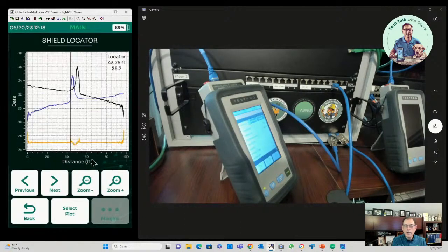Now I'm going to zoom back out. We can see these step TDR traces as well. Now these actually give us a little more detail because they jump up and then come back down, and they're a little more accurate in the details. And these will find very small details. So if you notice, the spike doesn't look very big here at this midpoint on the pulse TDR. It looks bigger on the step TDR because it's designed to detect smaller issues.